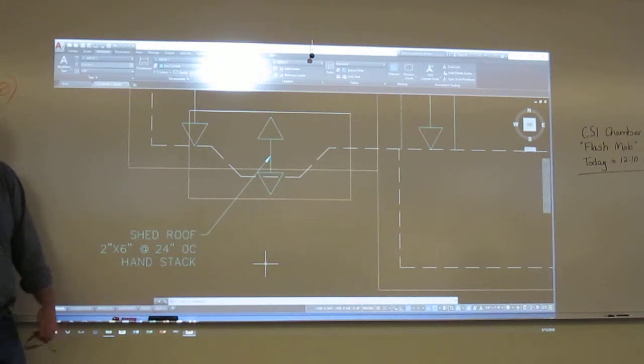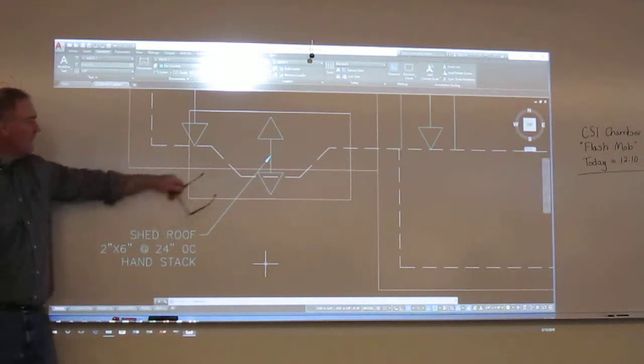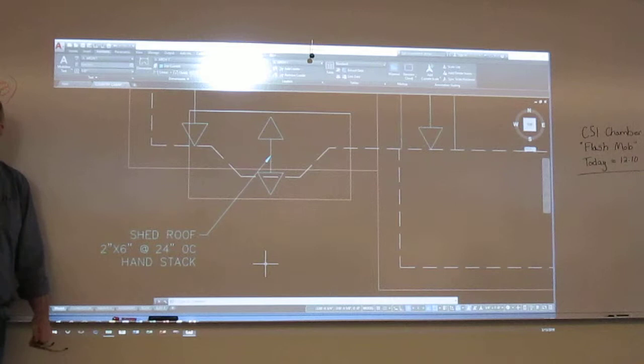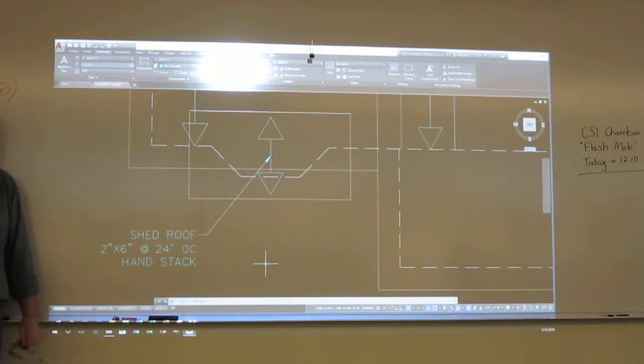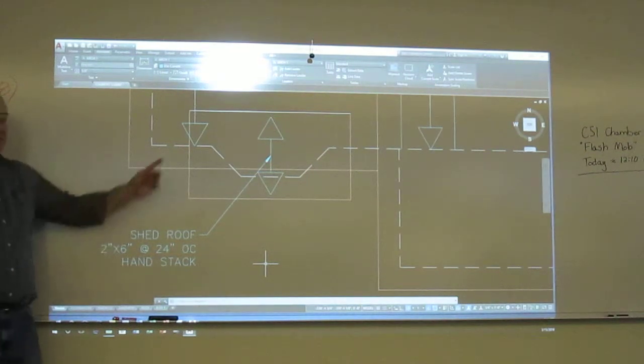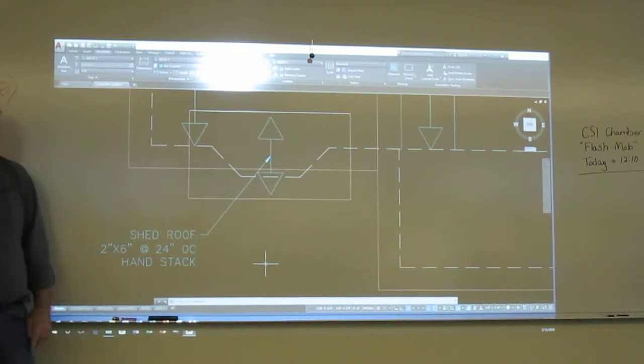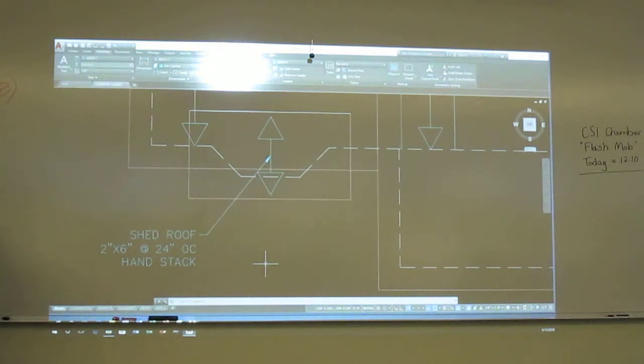Is there a way you can say, gee, I have no idea what goes here, what do you recommend? That's what we basically did by stopping those short. We basically said, you've got carte blanche here. Give me a shed roof. If I needed it built a certain way, I better be doing a section through it and telling them, you will build it this way. Then it'll be up to the general contractor to make sure his builders do it that way. That's what the client pays the general contractor to do. So you have to keep in mind that things will be changed, so if you really want something, you have to make a note and better do a drawn section.